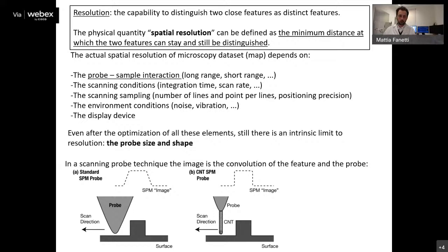So why is this important? Because in the case of scanning electron microscopy it is the same. If I have a sharp probe, I have high resolution. If I have a large probe, I don't. As I said, in modern SEMs, the typical size of the probe is about 1 nanometer, and so my resolution is also on that order of magnitude.